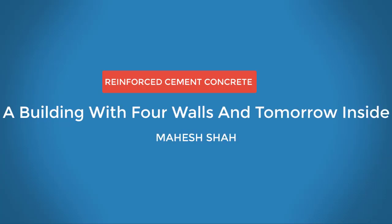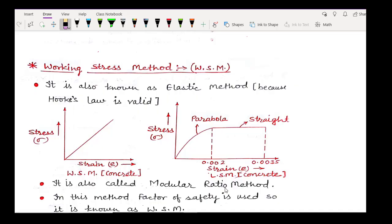The topic for today's online lecture will be working stress method, which is also known as WSM. In WSM, the term modular ratio is used as we have discussed in the earlier lectures. The term modular ratio, which was denoted by small m, will be used. And this method is also known as elastic method because Hooke's law is valid in this. As you know, Hooke's law is that stress is directly proportional to strain within elastic limit.